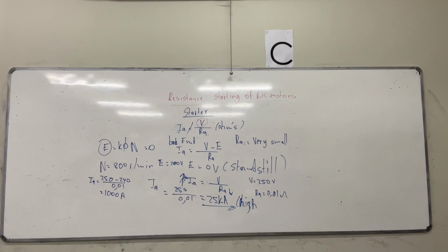So what happens? Ka start imoto uyibeka phi? Ku full resistance. Ine-notches le nto ne? Ka ilapha ku-position 1. Yabona le resistance yonke i-connected in series with the armature circuit. So ka start imoto uyibeka ku-position 1. Yabo i-resistance ka iku-position 1 iba ngakanani? Iba ninzi ne? Then ka i-position 2 yehlile by 1. Yabo? That is when the motor is starting to develop speed and it's producing EMF.